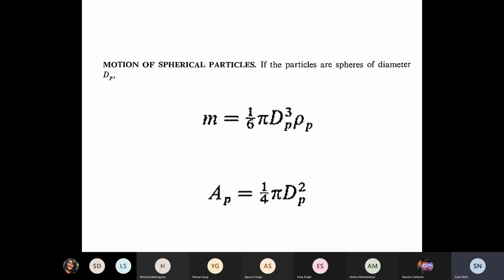Okay, because that is the characteristic property of the creeping flow regime. And now when you substitute for that in this general expression for the spherical particle, you should be able to derive the terminal velocity expression for the sphere in Stokes flow. That is the g with the dp squared, square on the diameter dependence.